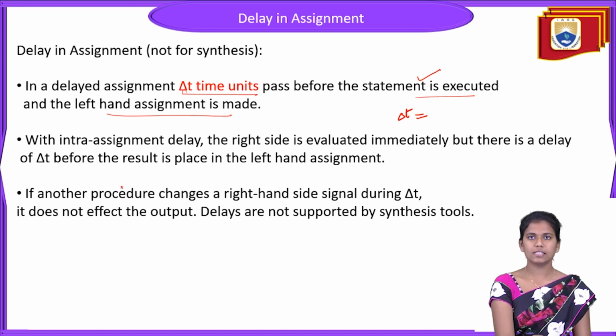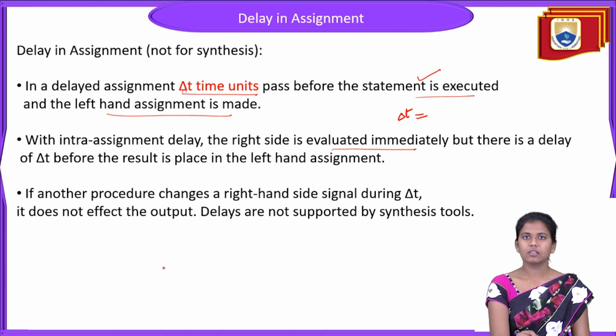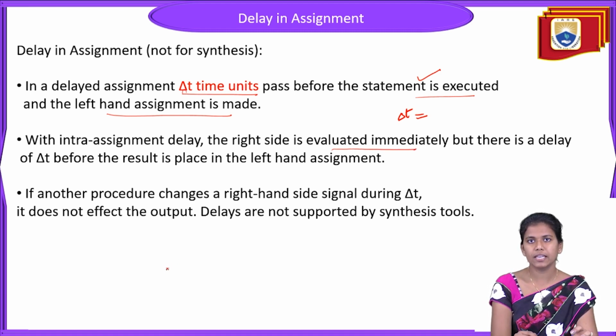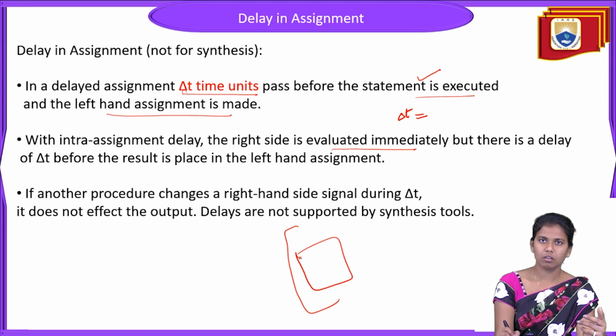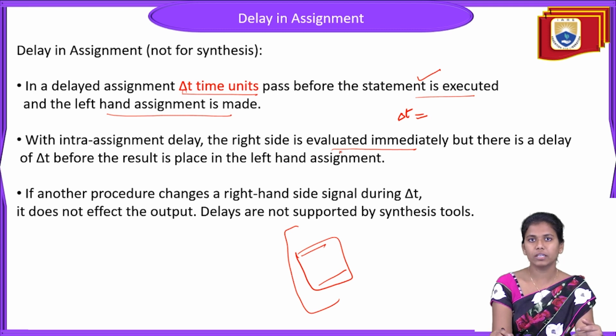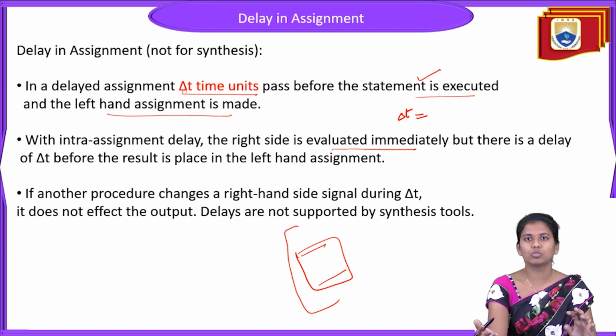With intra assignment delay, the right hand side is evaluated immediately. This is with respect to the delay assignment, and it is within the block, that is, within the initial block or the always block. Remember that the right hand side is evaluated immediately, whereas the time delays we mention on the left hand side will be processed only after the statement is executed.